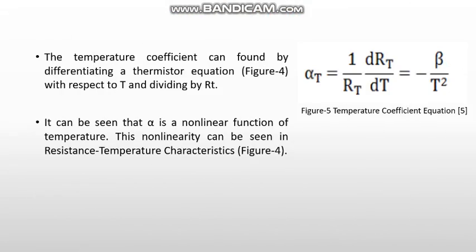And another important parameter for NTC sensor is a temperature coefficient. Temperature coefficient can be found by differentiating a thermistor equation with respect to T and dividing by RT. It can be seen that temperature coefficient is a nonlinear function of temperature.